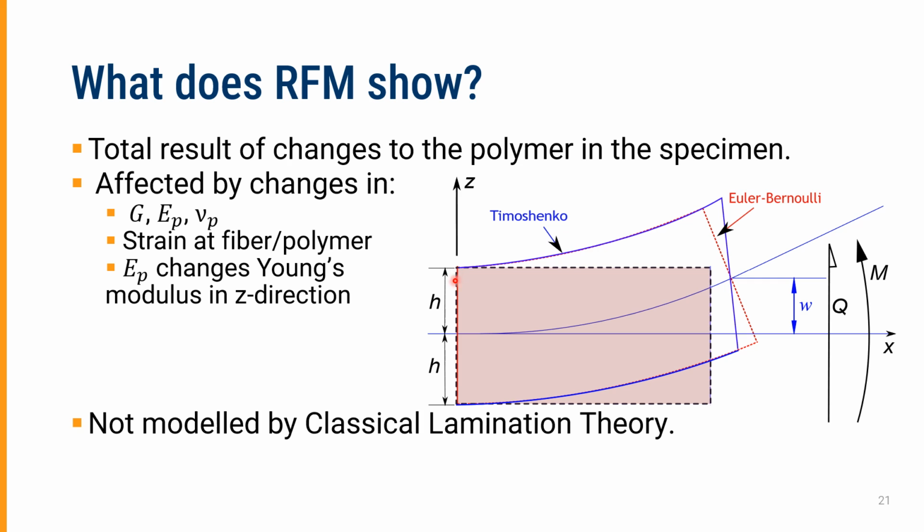So we're really only dealing with the polymer Young's modulus and whatever fraction of the volume is occupied by glass fibers, which are reinforcement fibers. It's a relatively small thing, but it will change a little bit the gross value of the Young's modulus.